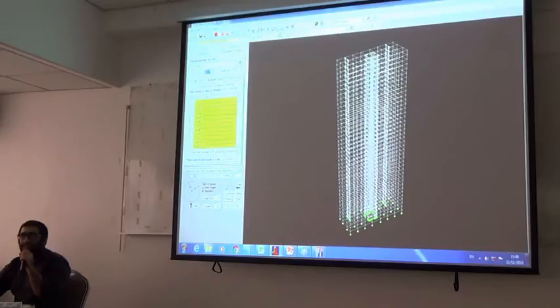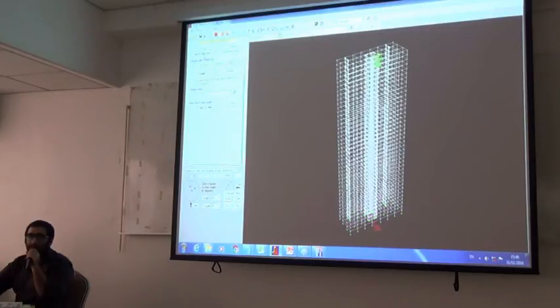So this was the section cut tab that you should already have with you right now, from where I got the section cut results. If you want to extract the drift results, you can extract them in the drift tab, the tab besides it. Right? You just select this tab, and then after you select the drift and deflection tab, you can go to the multiple results over here, this tab, right?